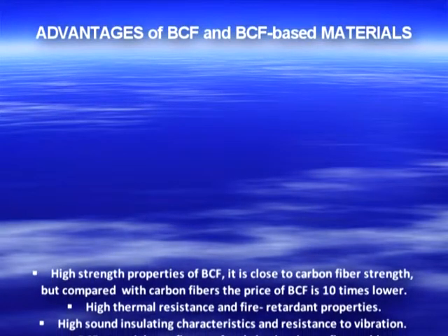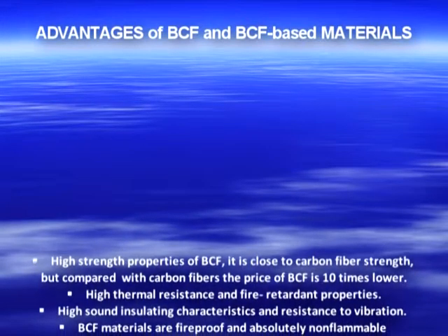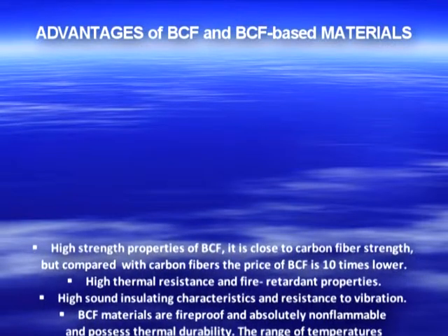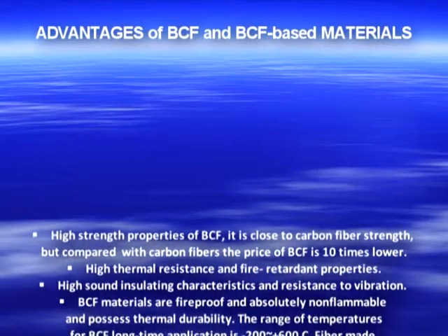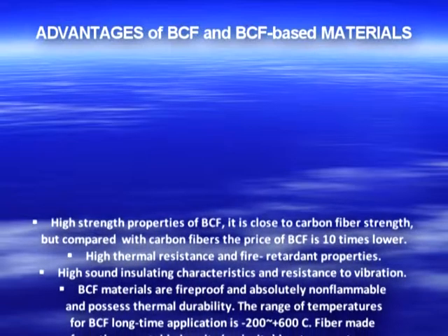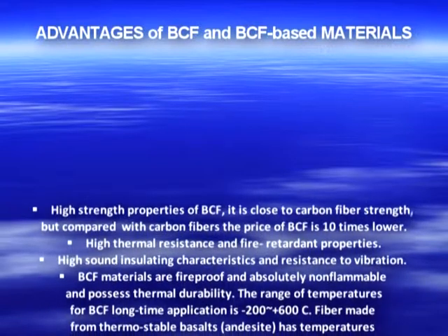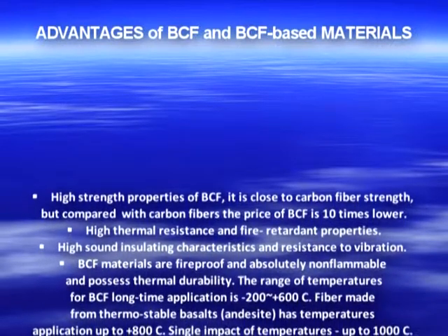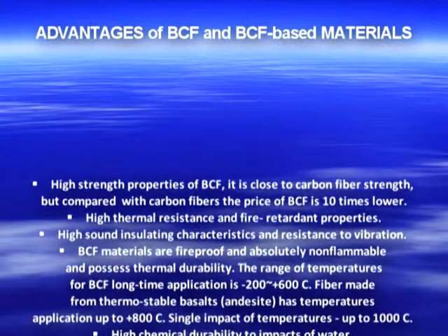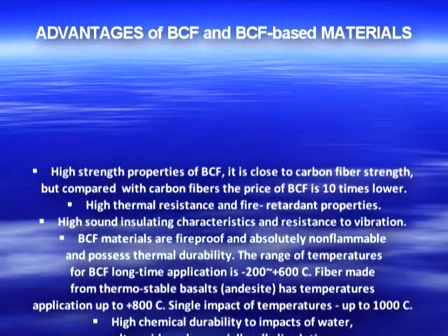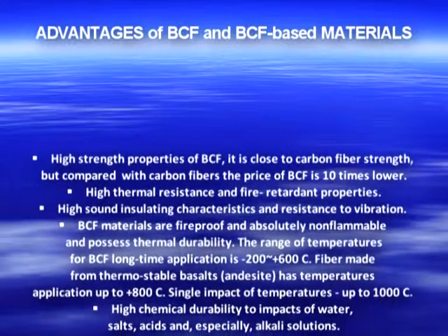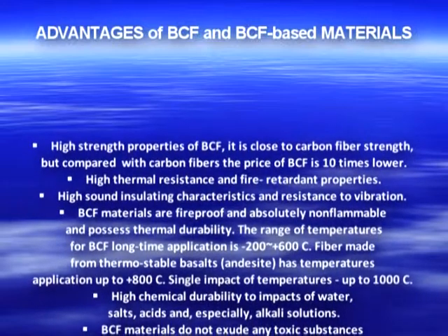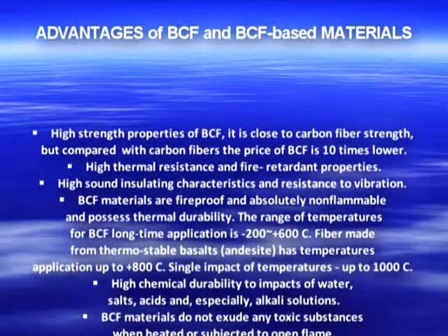Advantages of BCF and BCF-based materials. High strength properties of BCF. It is close to carbon fiber strength, but compared with carbon fibers, the price of BCF is 10 times lower. High thermal resistance and fire retardant properties. High sound insulating characteristics and resistant to vibration. High chemical durability to impacts of water, salts, acids and especially alkali solutions.